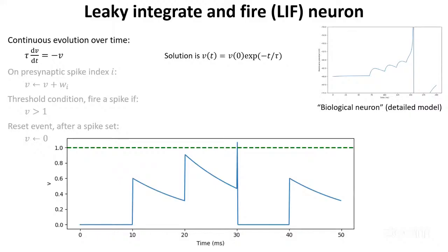So as the spike comes, now if you see, the potential will start to decrease. Potential will start to decrease, and that's why you need this kind of behavior, which we have in a leaky integrate and fire circuit. So leaky integrate and fire circuit is the one that we use to mimic the neurons nowadays. I mean, in the conventional neuron model used for spiking neural networks.